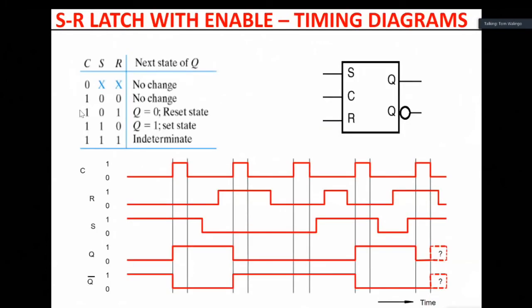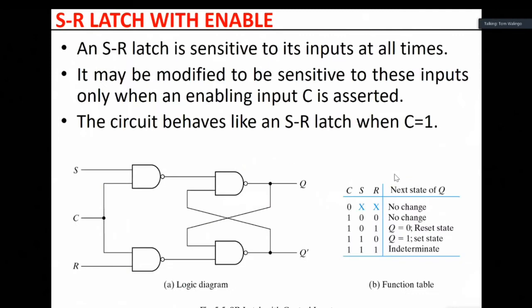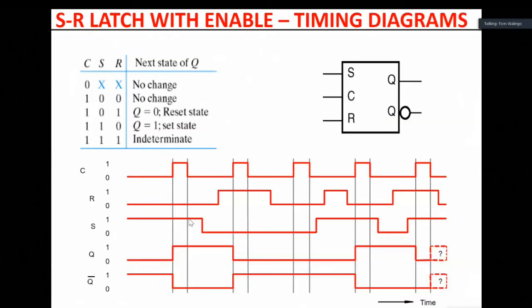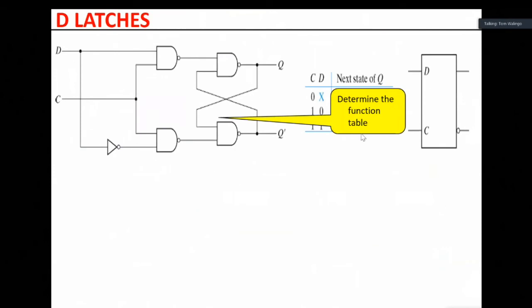It is the same diagram, but we have just done what Yashil has told us. There is the inverter that he talked about. And then we get what we call a D latch. We've just made sure that S and R are not the same and they are connected to D through an inverter. Now you've got D. D feeds the S and then it feeds the R.